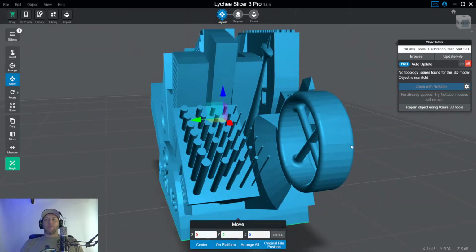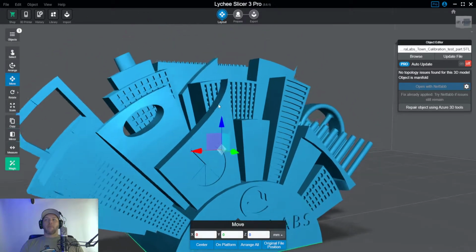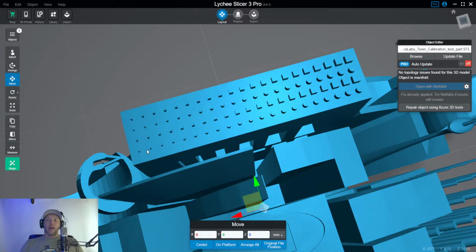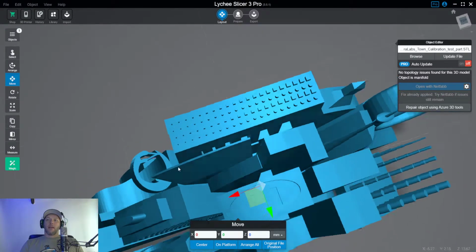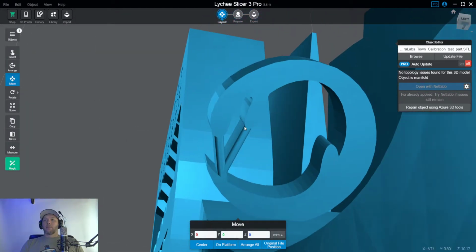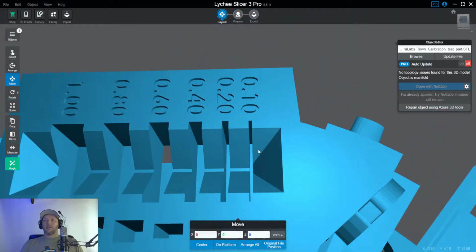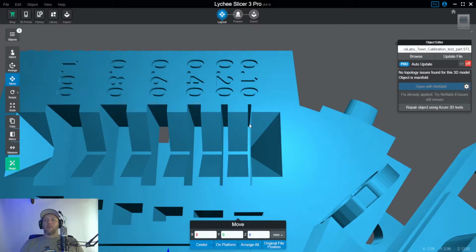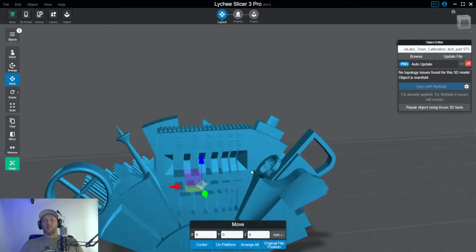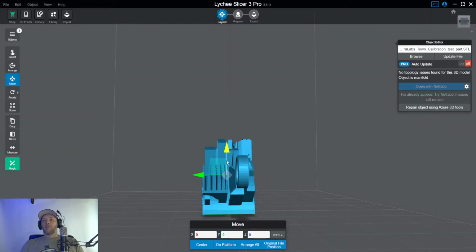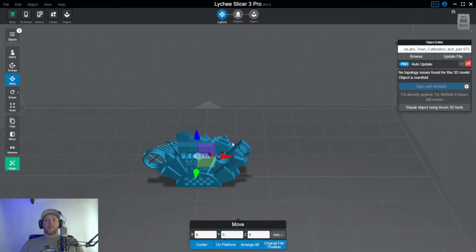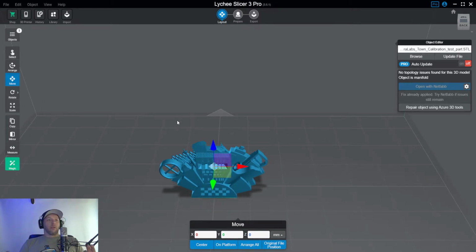After I'm done with that and I'm happy with those 3, I can poke around and see if I'm seeing these windows, how many of these am I seeing up on the top. Same with this little marker here. This is a pretty hard angle to print. So you can look at some of these other stats, I guess they're stats, I don't know the word, and see whether these indicators for 0.40 millimeters or 0.2 millimeters are showing up, or if they're buggered. But for the most part, I find that those 3 indicators nail it down for you. Get those 3 to show up, you're pretty much dialed in.